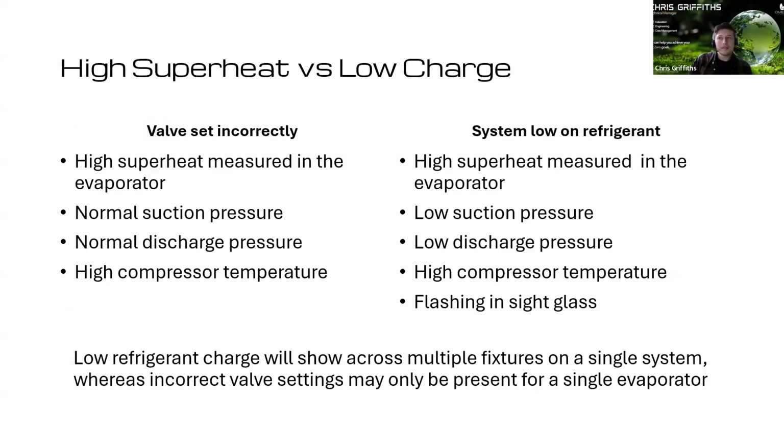The one thing, when I was an apprentice, trying to decide if something was an issue with high superheat versus low system charge always threw me. It was only after I probably came off the tools that I really started thinking and getting more to grips with it. So, just other symptoms, etc. But the main way to tell, I find, is: is the suction pressure okay? Is the discharge pressure okay?